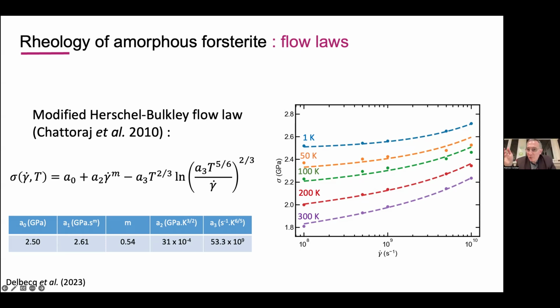Indeed, with 50% of iron, no amorphization. Completely brittle. With 25%, we find at the TEM a tiny layer of amorphous material, so there is a little bit, not so much. So indeed, we have an evolution. When we increase the iron content, the response to mechanical instability is fracture, not amorphization.